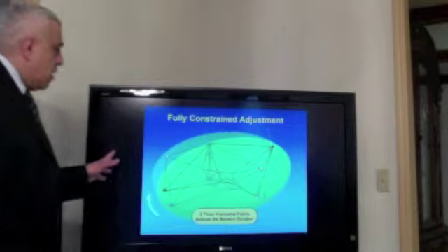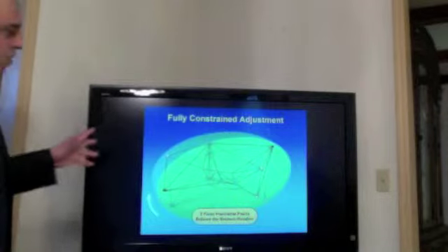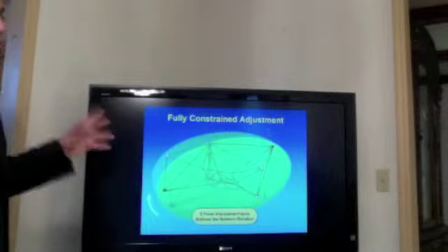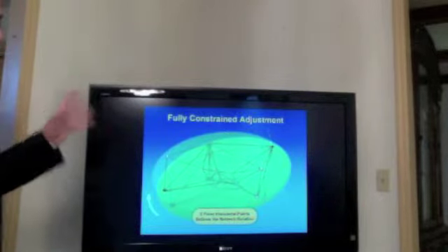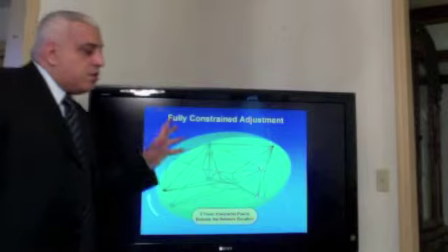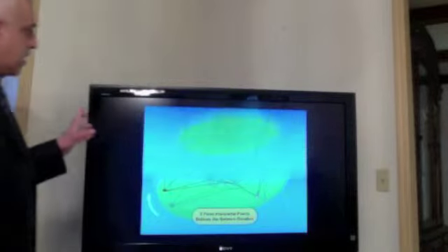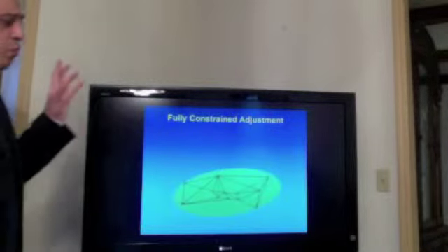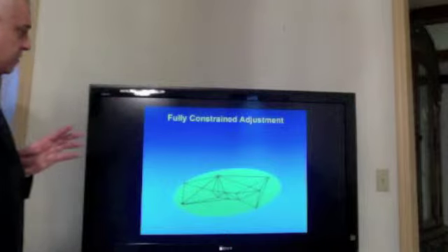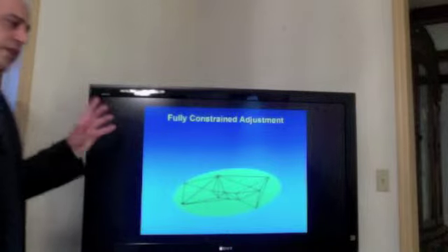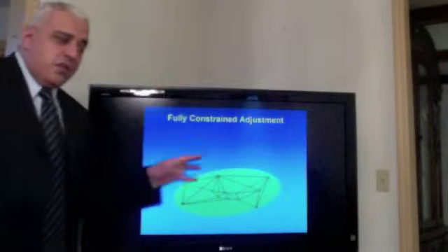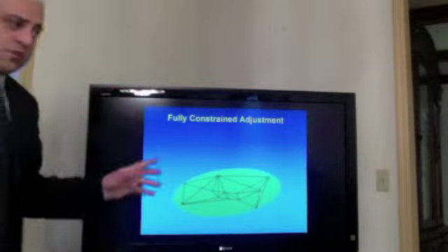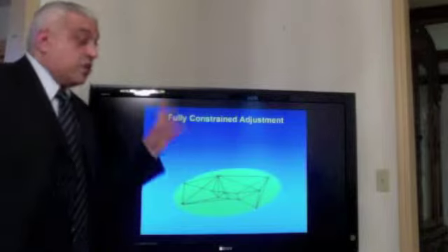And let us review again what we need for this adjustment process to happen. We need, as I told you, certain parameters to perform this phase. The parameters are, all in all, 7 parameters. If we break it down, it would be 3 rotations, 3 translations, and the scale.